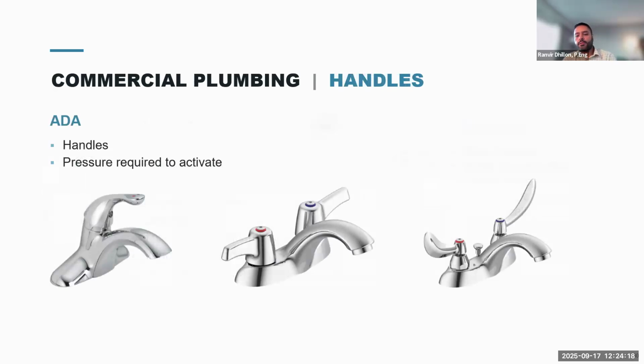If you go the manual route, you'll want to consider whether to go with a single handle or a two handle product. And then the ADA requires that a person must be able to turn on a faucet without twisting or straining the wrist and using less than 5 pounds of force. The ability to activate the water flow easily with only one hand makes it simpler for people with physical limitations to turn on the water. The user shouldn't have to grip or pinch the handle with force in order for water to flow. It needs to be able to be operated with a closed fist as well.